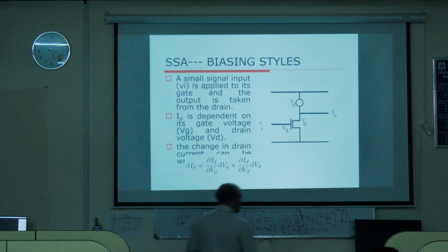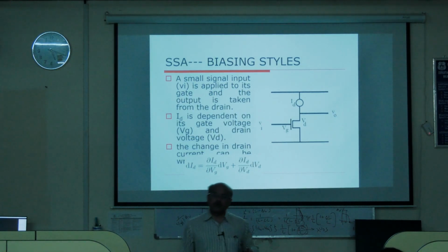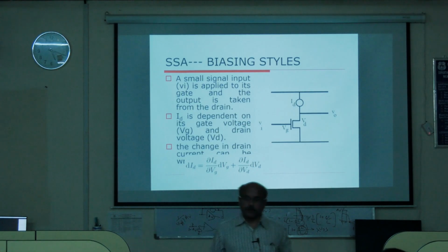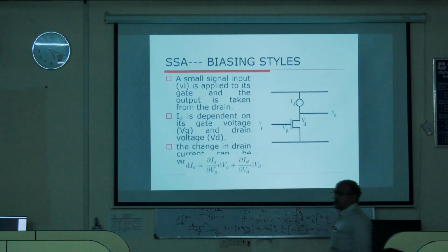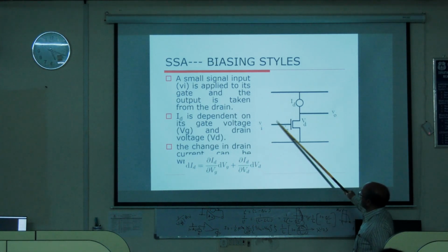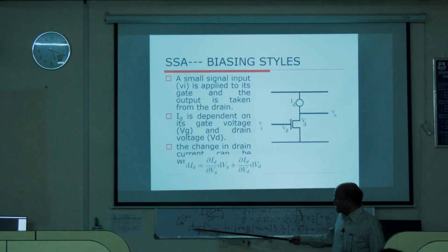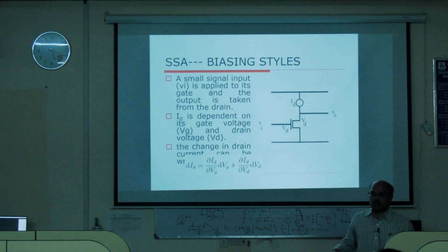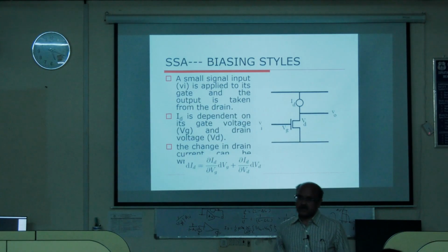Whenever there is a problem and you want to look at the solution, immediately what we have to look at is who is the culprit, who is causing the problem. The culprit is this capacitance CGD between the output and the input. Due to the Miller effect, it is getting multiplied by gain terms. The larger the gain, the larger you are increasing W, and therefore the larger the C, and it is even multiplied by gain terms.